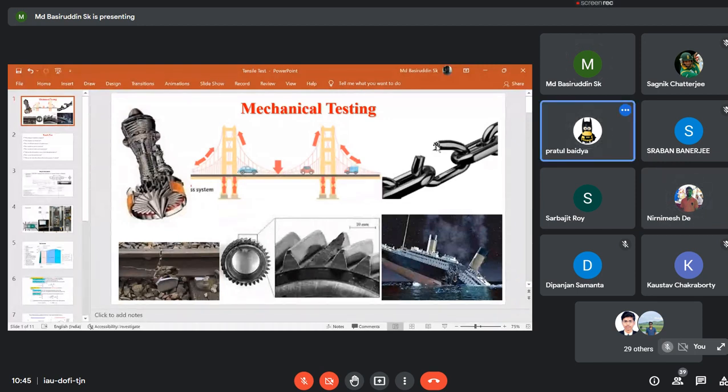For the glass. So have you seen the broken surface of glass? Is the surface flat, or can you find any haziness or a rough surface? It is flat. Yes, sir, it is flat. It is relatively flat, right, compared to the broken metal surface. So in that way, you can categorize fractures into two types, brittle fractures and ductile fractures.